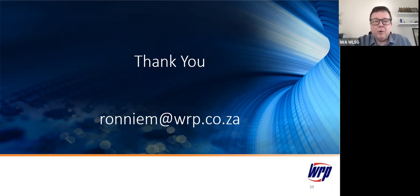Now, if anybody has any questions for Ronnie on anything from the webinar or anything else, then please use the chat function, which is at the bottom of your screens, and then you can type your question in there. We've had one question already, Ronnie, from Michael, and Michael said, with society becoming more 24/7, at least pre-COVID, I would assume nighttime consumption is now higher than ever before. How would you take account of this, as surely genuine nighttime consumption can look like leakage on DMA flow graphs?